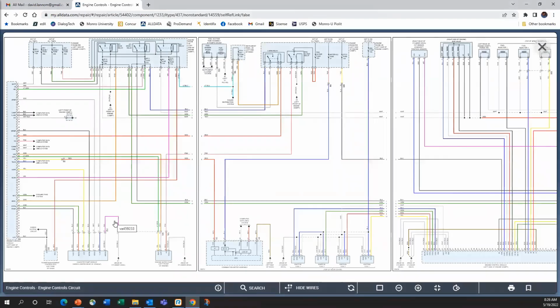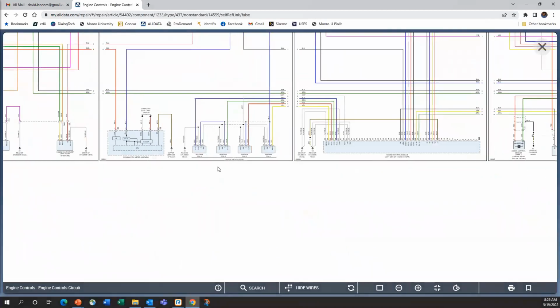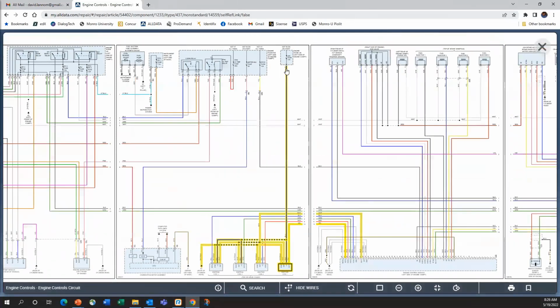Well, maybe it's a concern, maybe it's not, because in any case, whatever it is that I'm going to decide to work on, let's say I believe I've got a bad ignition coil, but I need to know the signals, I'm still able to go and look specifically at ignition coils 1 through 5. And in the same way, if I highlight that component, there's everything I need for that ignition coil to work. So we can follow it all the way back up and we see that the ignition coil gets fused power. And then we could follow it back into the PCM to see the ignition drivers.